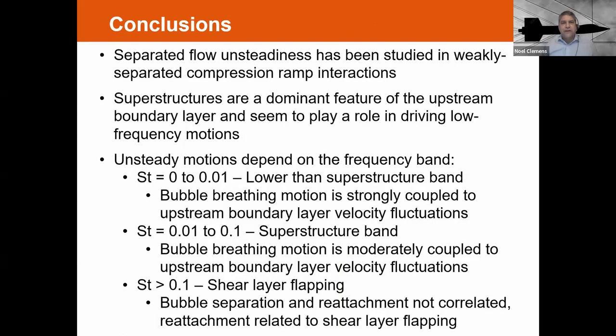Okay, so I'm ready to conclude. We've been studying the separated flow unsteadiness in weakly separated compression ramp interactions, and I say weakly separated because they are about 2 delta in extent, and as you get to 4 delta, we would consider that a stronger interaction.